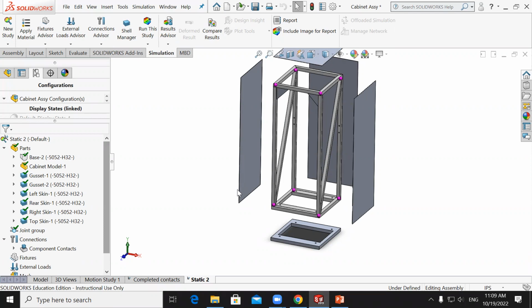And then we go to your applied material. We have to create a contact set. Okay, the steps we have done: the material, and we changed the element type to be solid, shell, and beam.